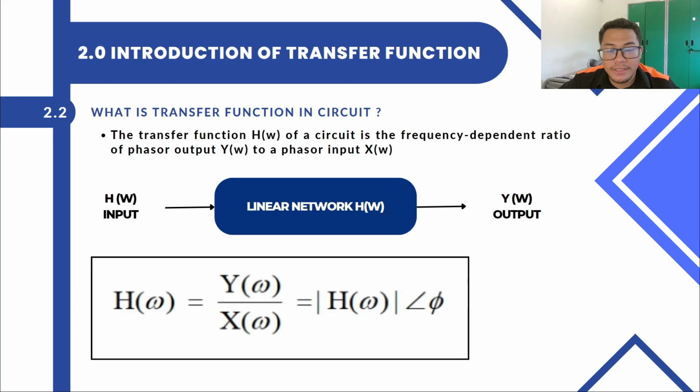The transfer function can be decomposed into its magnitude, |H(omega)|, and phase, providing insight into both the amplitude scaling and phase shifting effect of the system on the input signal. This forms the basis for constructing the Bode plot, which graphically represents the magnitude and phase across a range of frequencies, helping engineers to understand and design system behavior.